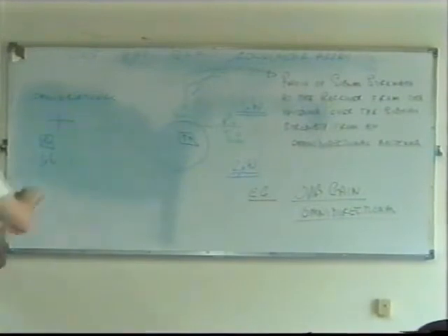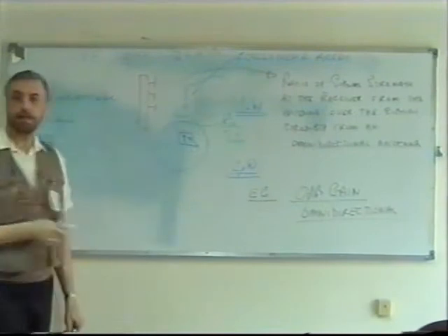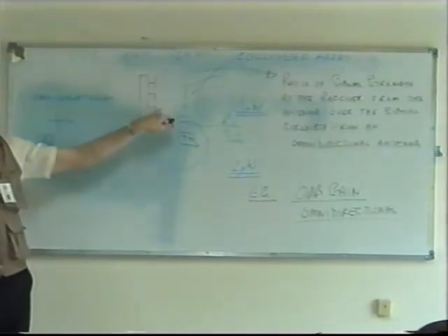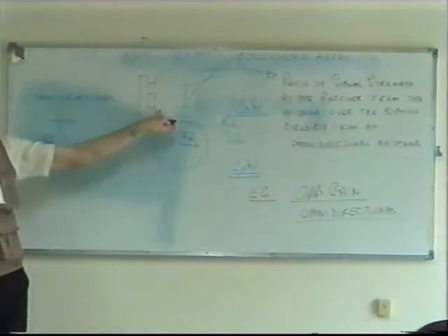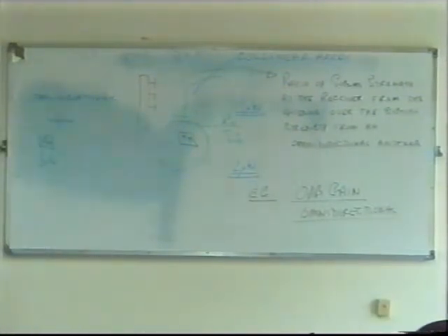Well, you've got to be a little bit careful, obviously. You're talking about 2 elements of 1 antenna, I think, 2 active elements. For instance, if I have a stacked array, remember our stacked array? How many antennas is that? No, it's 1. It's a 3-element single antenna. Don't get confused. If you connect each of these dipoles to the same transmitter, it becomes 1 antenna. Maybe with a multi-coupler or multiplexer, but it's combined.